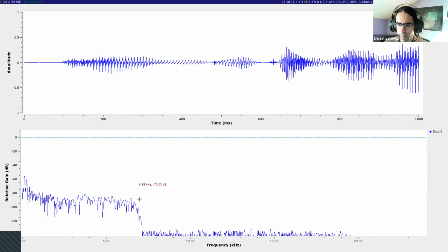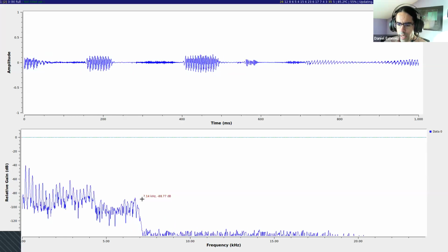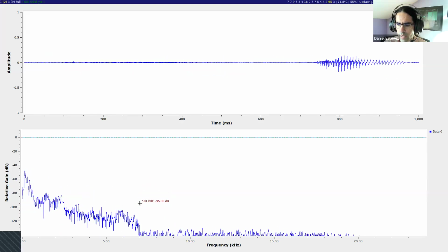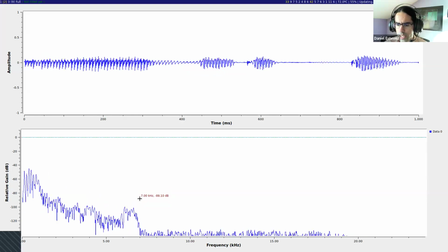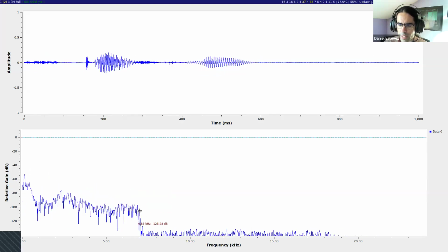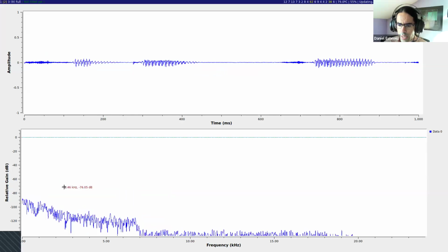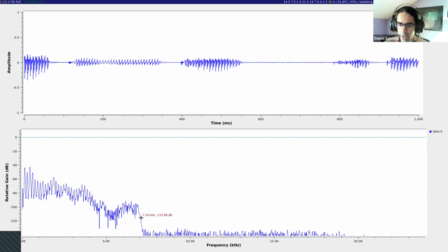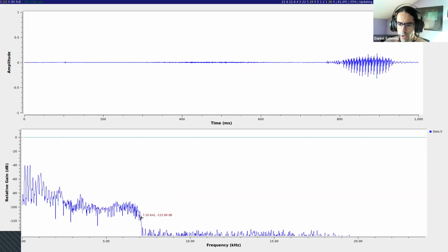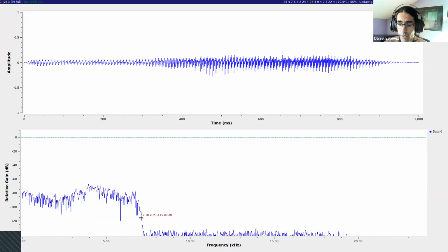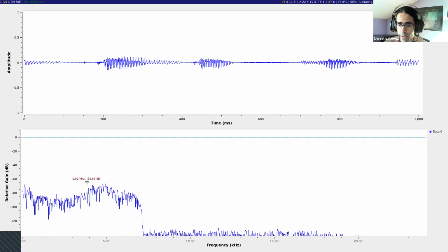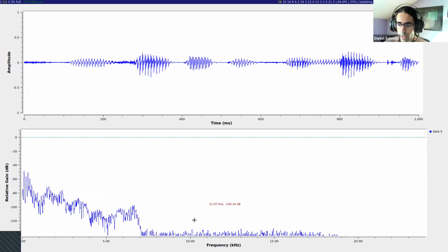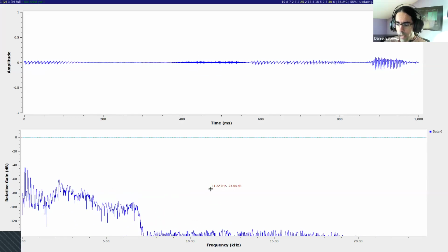And you can realize something about the headset I'm using: since it's a wireless headset and transmitting a lot of data wirelessly is costly, it has a low pass filter, so it's not sampling all my voice. It's cutting it at about 7 kilohertz, because most of the spectral content of a human voice is in this frequency range. But if we had a different microphone, we could see other things in here.